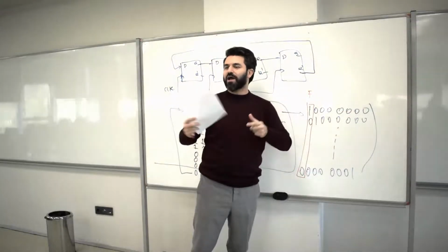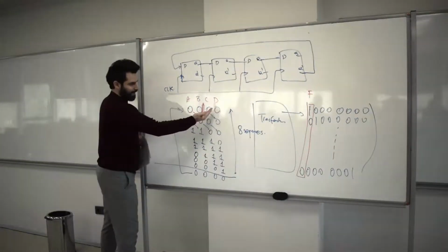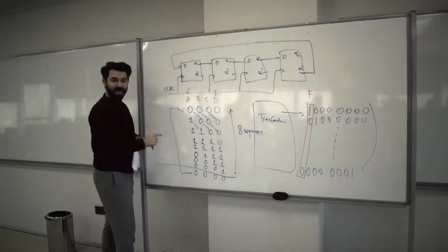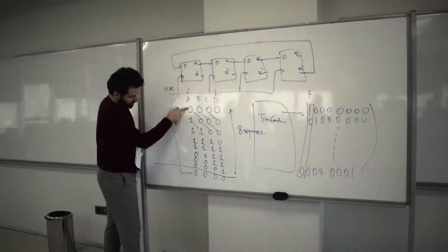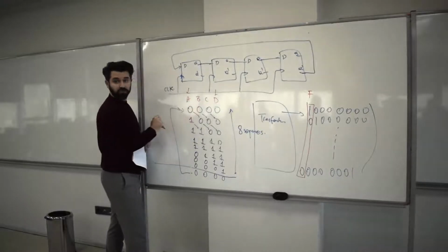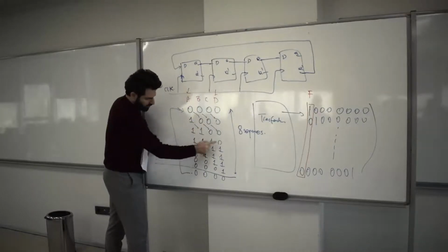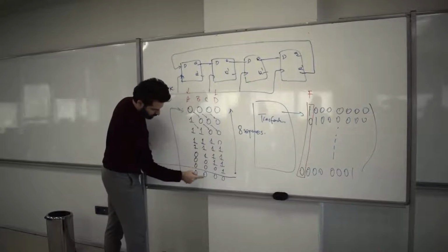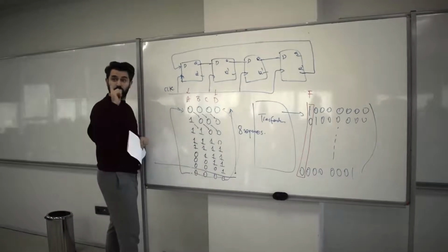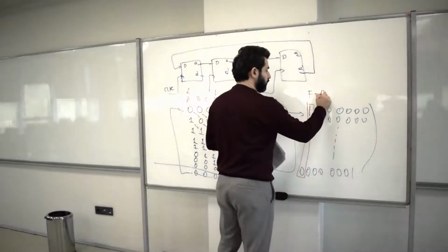Okay, that's going to create 8 different maps. If you've got time, please go and verify it. But if you look at these inputs, one of the things that I realized, I just took A and D for example. Just look at these columns, this one and that one. There's only one place where both of them are zeros. You see, this is the place where they are both zeros. The rest of the locations are 1, 0, 1, 0, 1, 0, 1, and then 1, 0, 1, 0, 1, 0, 1. That's it. Right? This is the copy of the first. So you can see that there's only one place where A is 0 and D is 0. So therefore, I'm going to just say F is equal to A prime D prime.